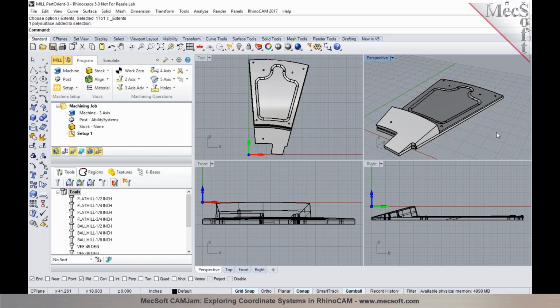And the second point is, one of the things that Uday did was he said a combination of transformations. One is using the CAD transformation tools, and then the second thing that you could use is the CAM transformation. I wanted to point out the difference. The CAD transformation tools only work with the geometry that you're machining, or the part geometry, while the CAM transformation allows you to transform both the part and the stock together.